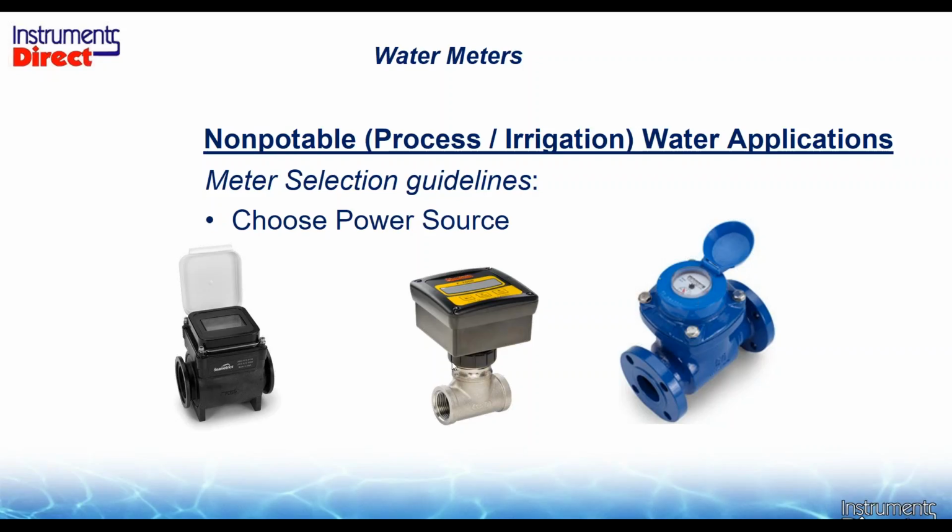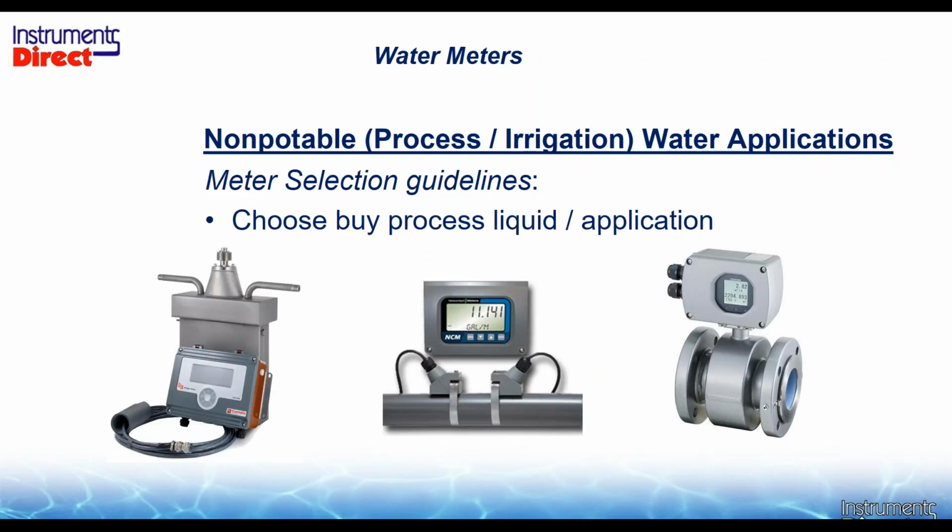How about a paddle wheel flow meter? Well, you can get a paddle wheel flow meter in many cases there where the paddle itself generates enough signal to get a display, or if you need to have some kind of outputs there, then we need to add a battery to the system. So choose your flow meter by the power source for your particular application.